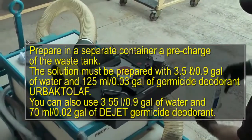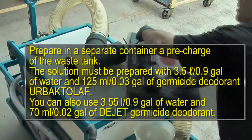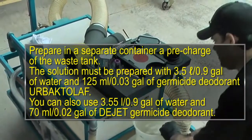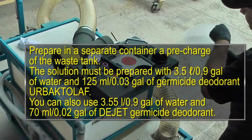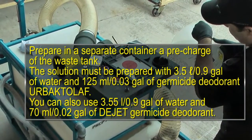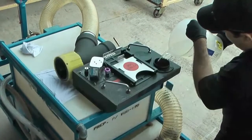Prepare in a separate container a pre-charge of the waste tank with a solution of 3.5 liters of water and 125 milliliters of germicide deodorant or Bactolaf, or 3.55 liters of water and 70 milliliters of D-Jet germicide deodorant.